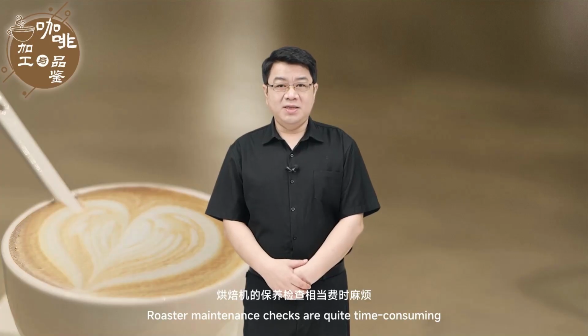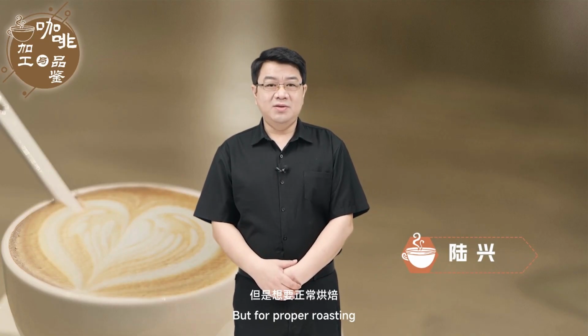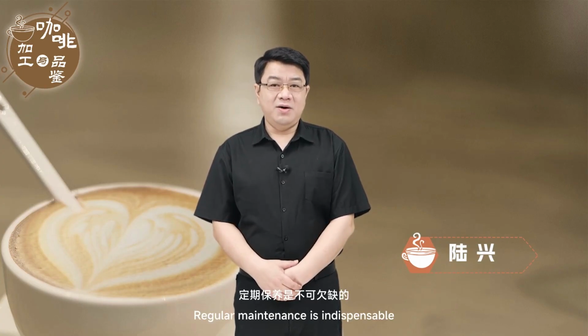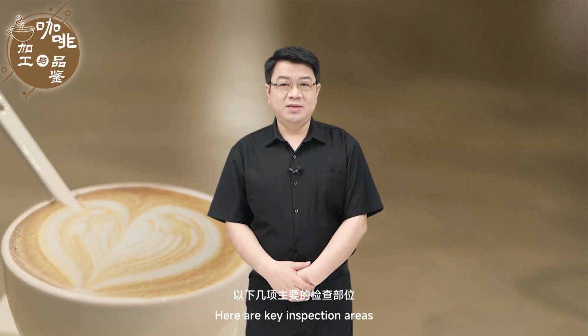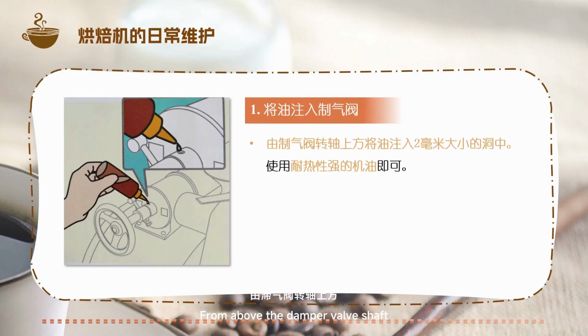Roaster maintenance checks are quite time-consuming, so they're often neglected. But for proper roasting, regular maintenance is indispensable. Here are key inspection areas and maintenance methods. 1. Oil the damper valve. From above the damper valve shaft, inject oil into the 2 mm hole using heat-resistant machine oil.